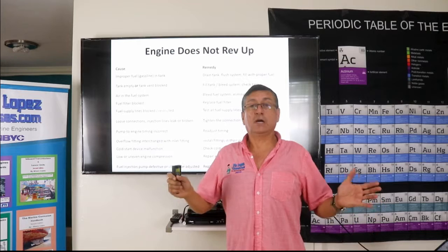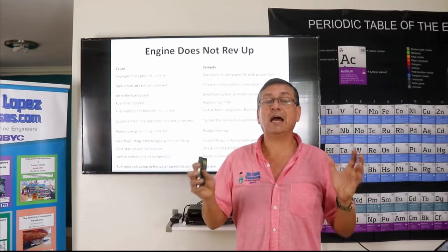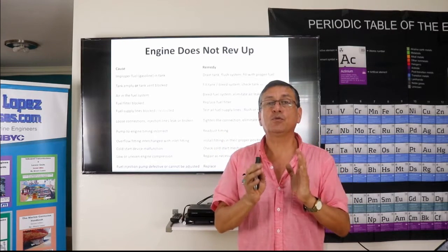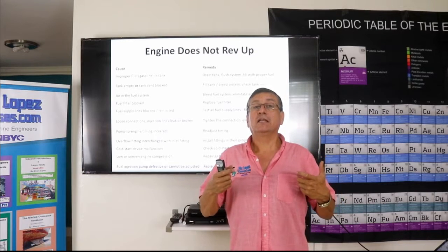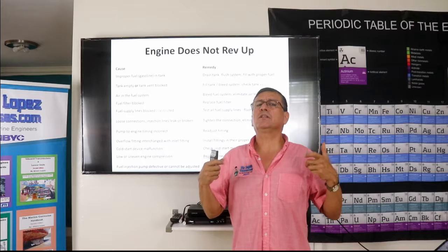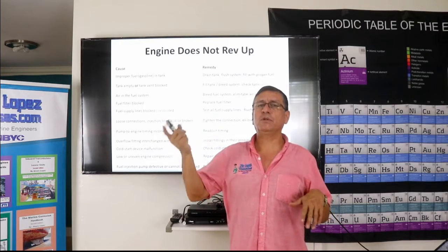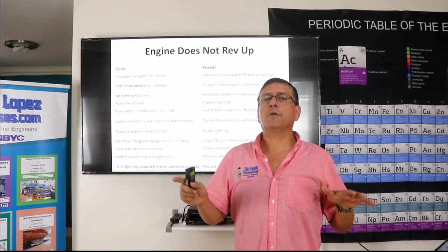Yeah, those are the typical problems related with the fuel system, and you need to be familiarized with those problems and with the solution. For that reason, it's important to ask the captain, to ask the customer. What about the temperature in idle? What about the temperature in wide open throttle? What about the RPMs in idle?